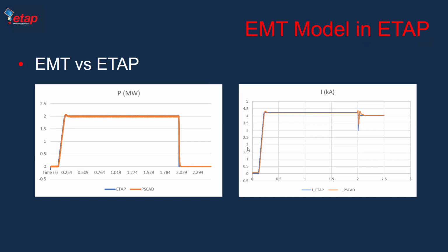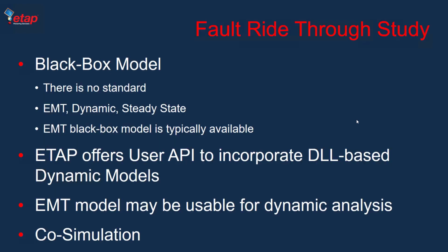As you see, the response of PSCAD and ETAP for the vendor-specific model is almost identical. Definitely, there are certain transients that you can only see in the EMT analysis, and you see it here. But when you're looking at how the system in general behaves, the trends of the voltages, currents, and powers, they match very much.